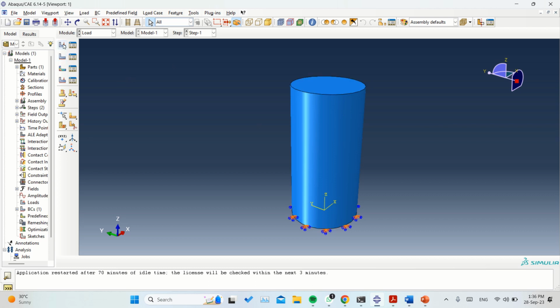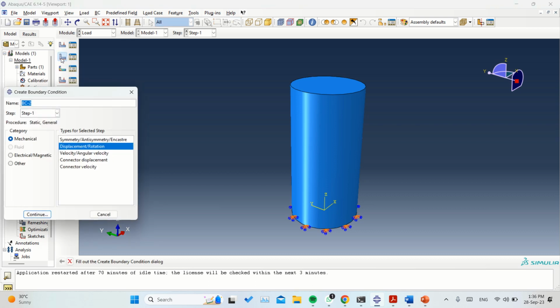Now apply the load. Load may be applied in the form of either kilonewton or in the form of displacement. That is the stiffness method. We have not studied it, okay? But I would like to apply load by using displacement, not by using force. That gives better results. That gives minimum errors while running the model. So I will give